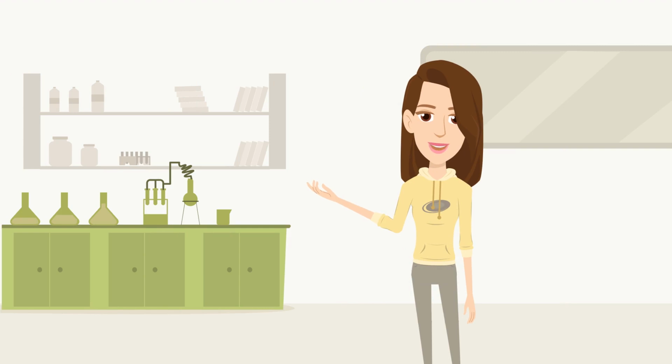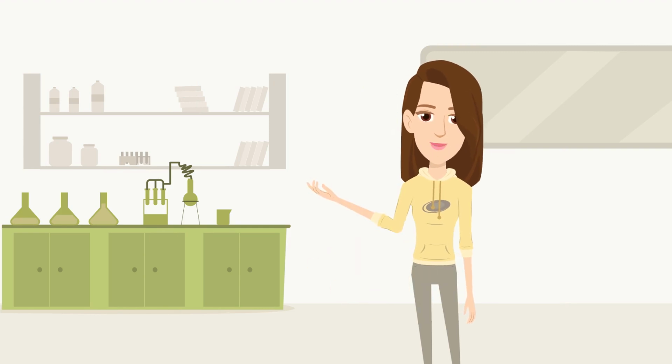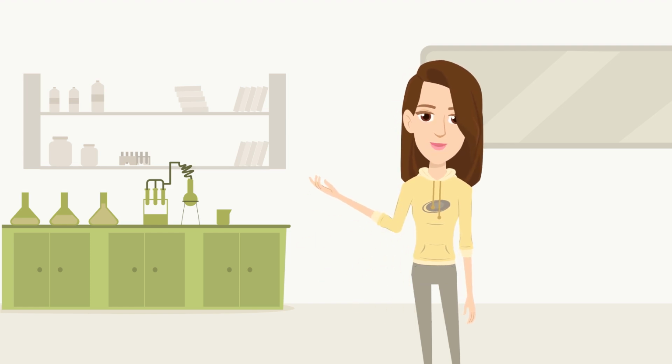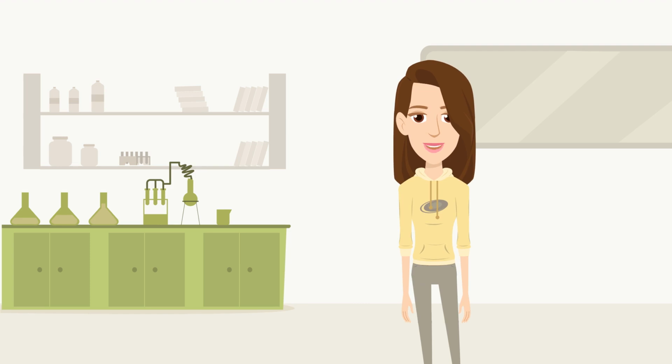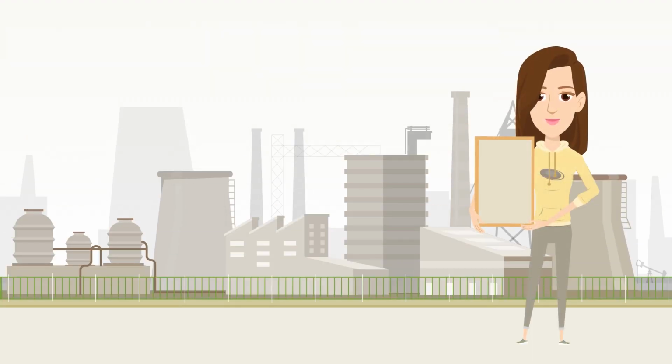Using materials with longer life cycles that can be recycled or reused. Minimizing components that are difficult to process or recycle, such as material mixtures, toxic or hazardous substances. Designing products that can be easily disassembled into parts or modules for easy repair and replacement, which in turn extends the life of the product.